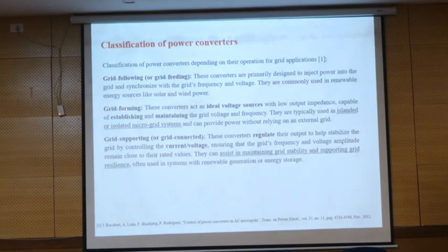We are responsible to provide the power to the grid, and the main idea is to provide the maximum active power. We mentioned, for example, in the Atacama Desert, each unit of the generator was 1 megawatt active power and 50 kilowatt reactive power. The reactive power is for keeping the voltage stability in the system. But the main idea is to transfer the active power from the generation to the load center.